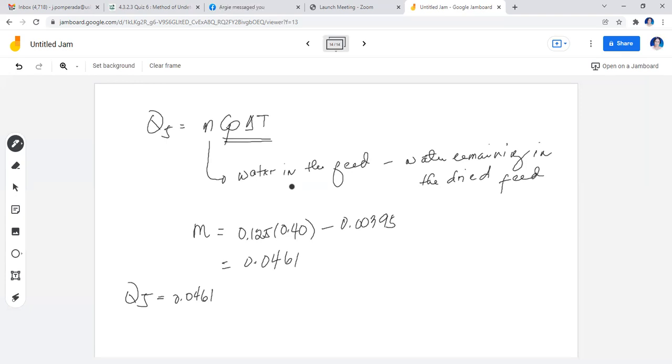So in this case, we will modify the CP delta T that we have here, but we will add two more terms. The first thing that we're going to account for is the sensible heat for that particular liquid water to raise its temperature to 295 from the datum temperature, which is 273, because we've been using the datum temperature, which is 273.